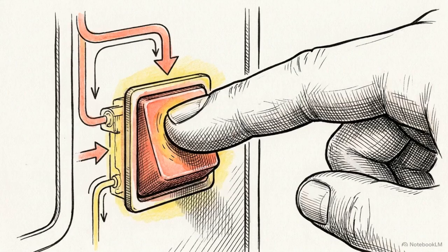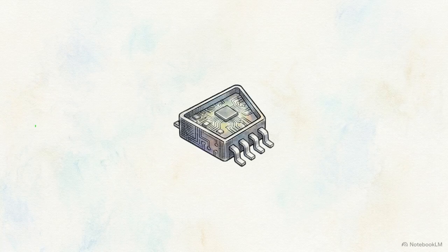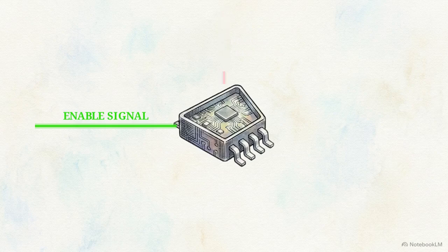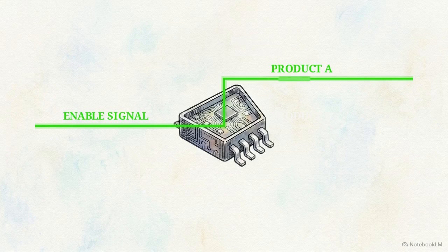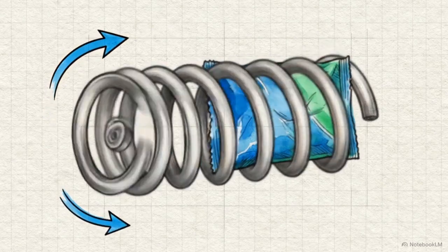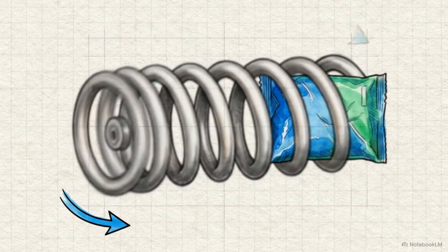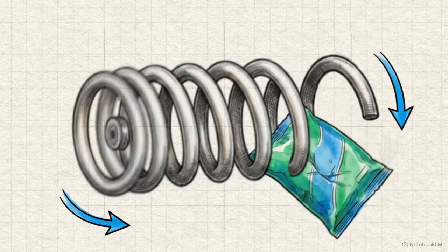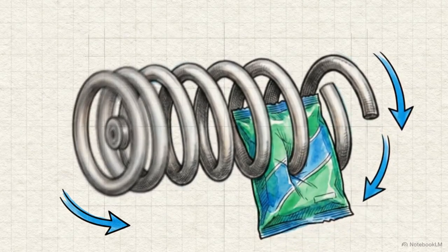With the payment cleared, you press the button for your chosen product. Deep inside, this diagram visualizes a demultiplexer taking your specific button press and routing the incoming electrical signal down one of 3 branching paths, directing it to the correct product subcircuit. That signal hits a D flip-flop, triggering a short, highly active electrical pulse to the physical actuator. The metal coil spins, and your snack drops.